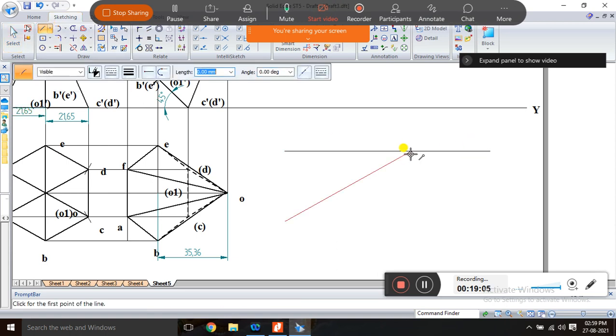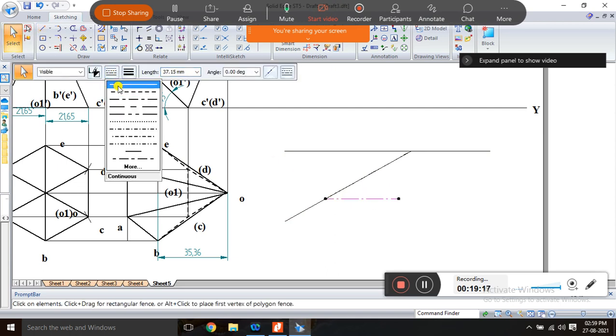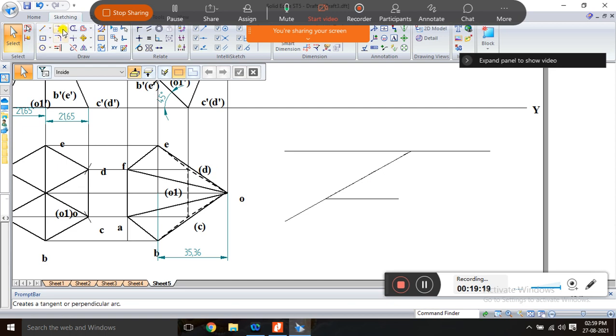So take the axis from the 50 as usual. First draw it, next draw the locus line. That's why it is called a locus. Draw the locus line. Next, check the compass, place it on O and stretch up to O1 for the top position. Its distance is 35.36.